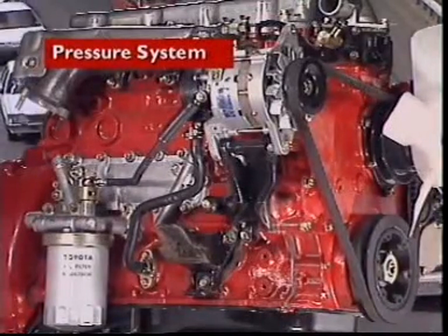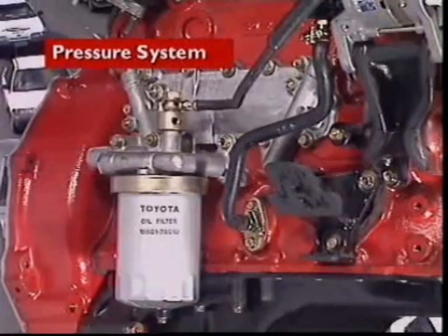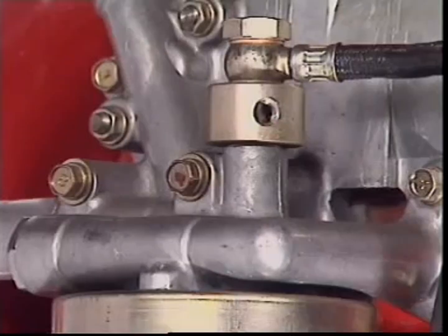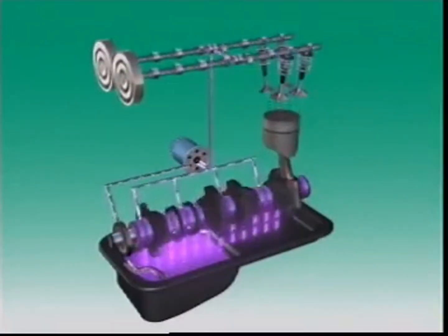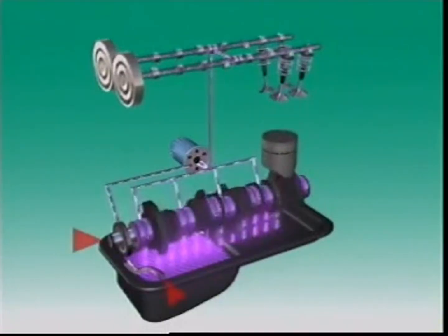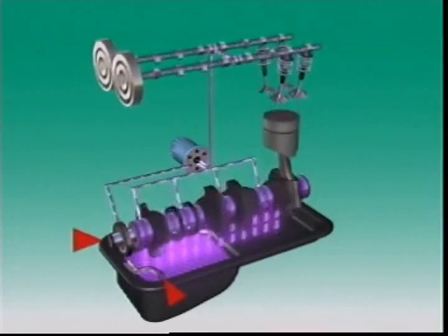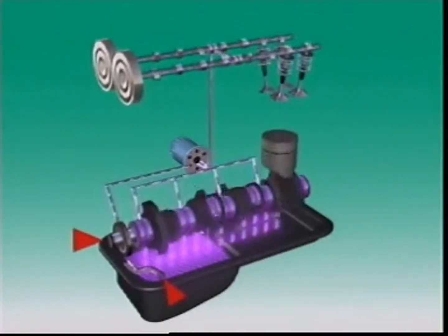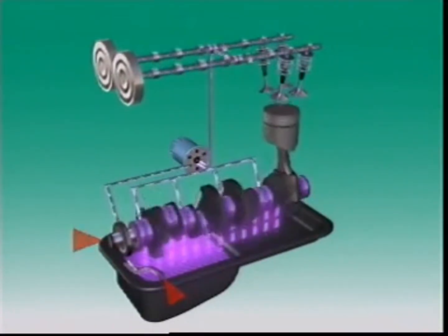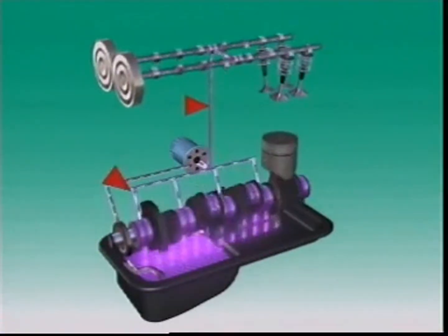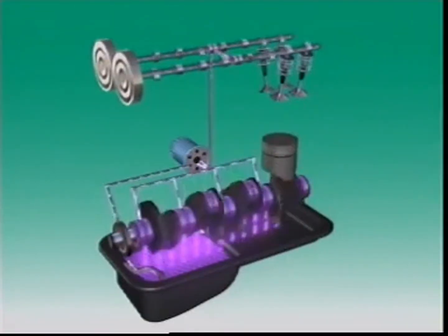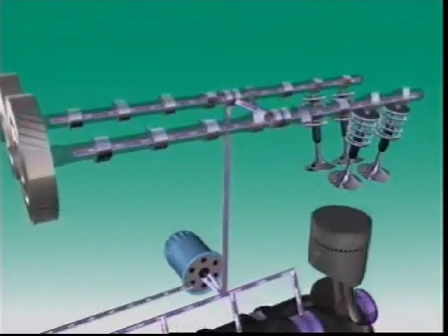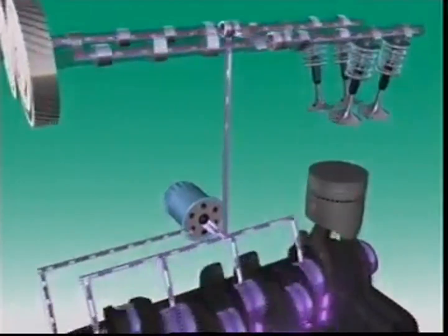Modern vehicle engines use a pressure or force feed lubrication system where the oil is forced around the engine under pressure. Let's look at petrol engines first. Oil won't flow up into the engine by itself, so a pump collects it through a pickup tube and a strainer and forces it through an oil filter, then into passageways in the engine block called galleries. The galleries allow oil to be fed to the camshaft bearings, the valve mechanism and the crankshaft main bearings.